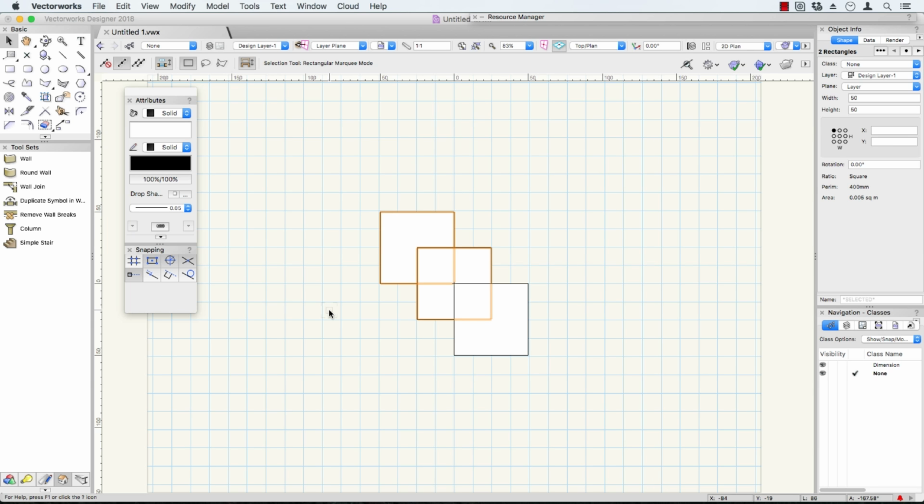It's really important that you learn how to select objects, because without it, we can't do all the other stuff. I'd like to talk to you now about keyboard shortcuts. Some people like to use keyboard shortcuts. You don't have to, but if you're interested in learning how to speed up your Vectorworks drawing, learning some keyboard shortcuts can be very useful. Some of the tools, like the text tool here, have a hotkey. In this case, it's key number 1 on your keyboard. See in the brackets it's got text and a number 1.